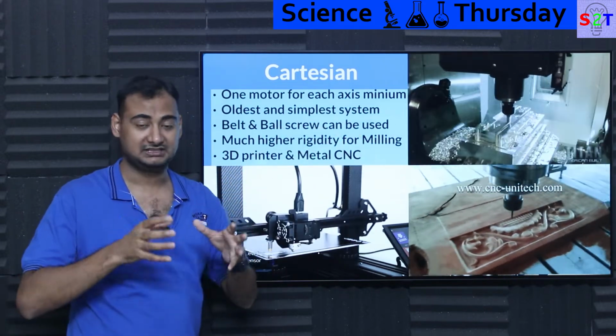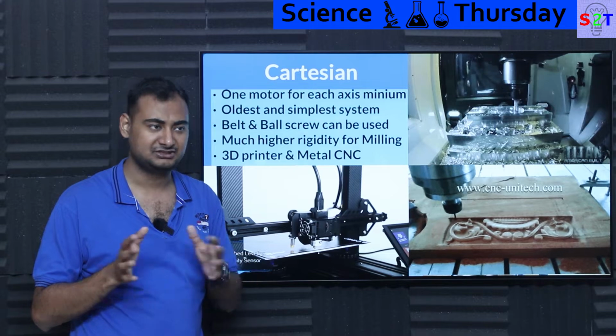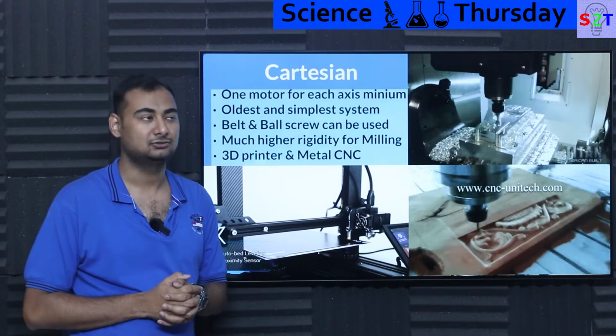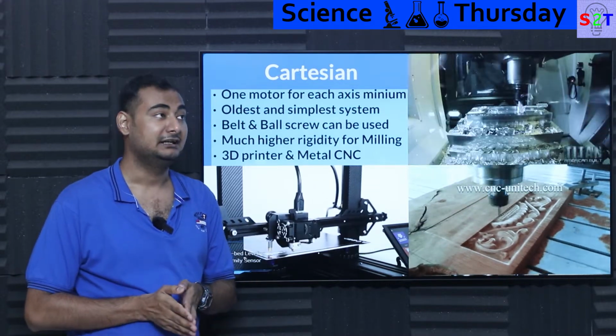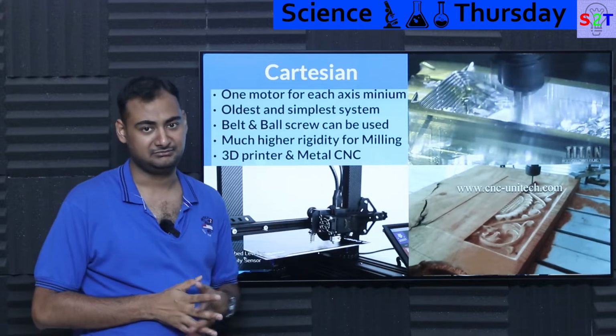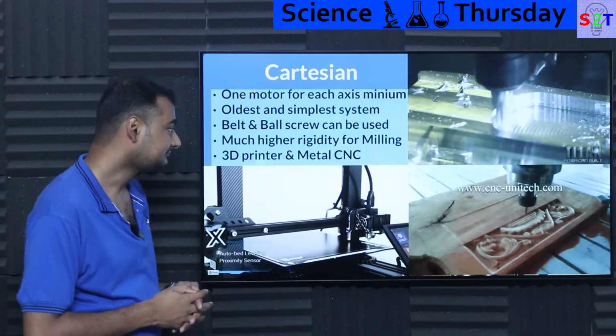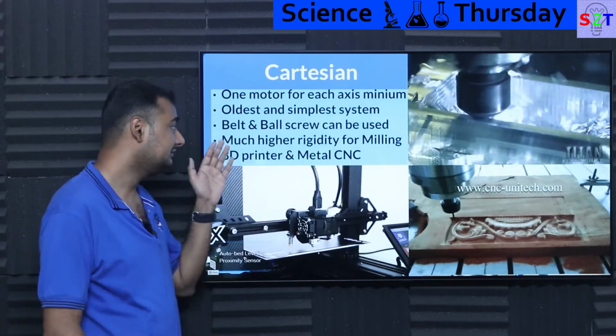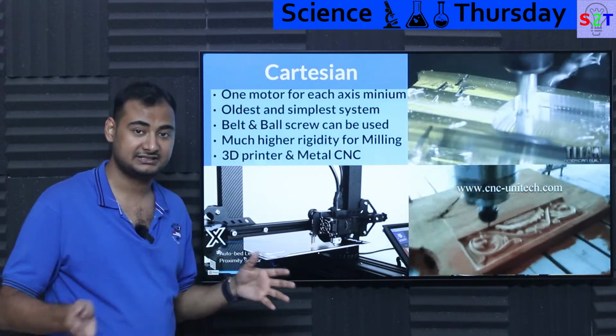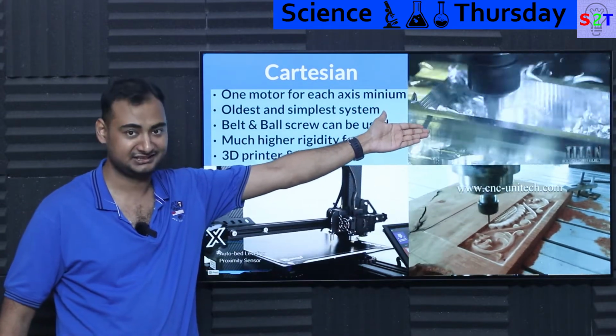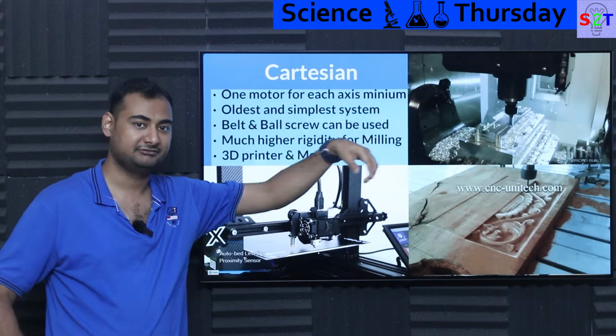That gantry will move. Basically, if you are building that up with something sloppy, it will shake, and good luck getting a good result out of it, and there is a very good chance you will break your end mill the moment you touch it. So that's why if you need a rigid structure, you can go into ball screws, and that's how all CNC was. That's how you are achieving something like this.